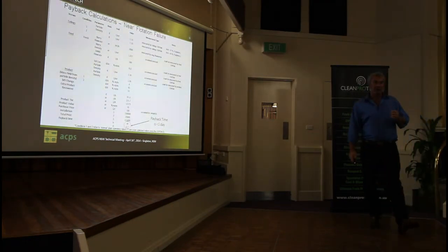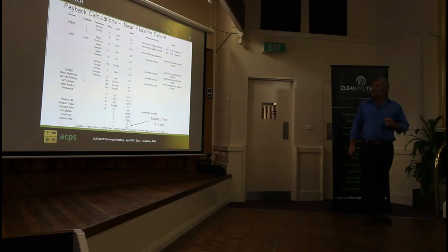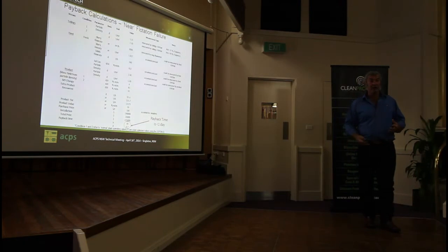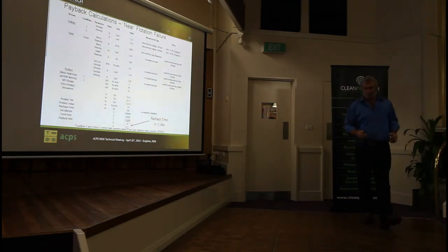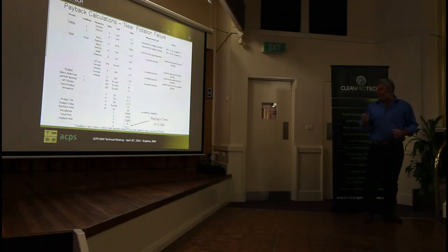We have also seen, both at Bloomfield and other places, what we call the near flotation failure. It's where something happens like a blockage in the collector dose rate. There's still coal coming in, there's still frother going in. You're still producing froth off a flotation cell. Looks okay? Well, you could pick it up by looking at the filter and that sort of thing, but often it goes unnoticed for quite some time. Because you're looking at the particle density, you would pick that up immediately, and hopefully you'll respond much quicker.